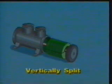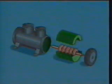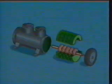One type consists of a cylinder with a removable end plate. When the end plate is removed, the shaft, impellers, and diffusers can slide out, much like you'd take the batteries out of a flashlight. These working parts are often called the bundle. The bundle is horizontally split to allow installation or removal of the rotor as a unit.